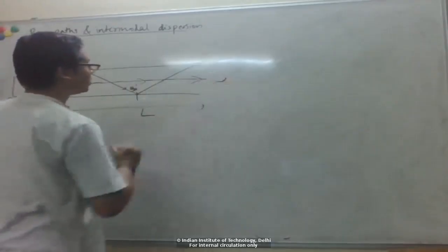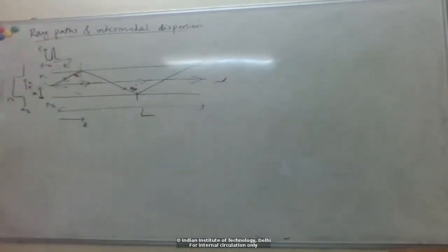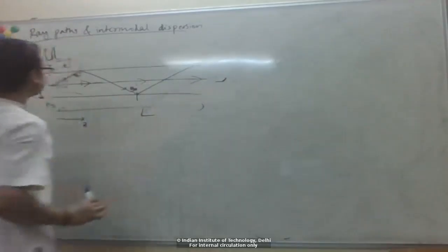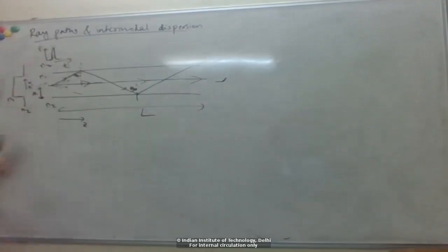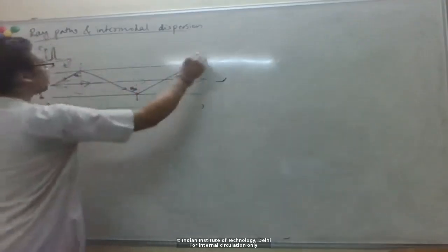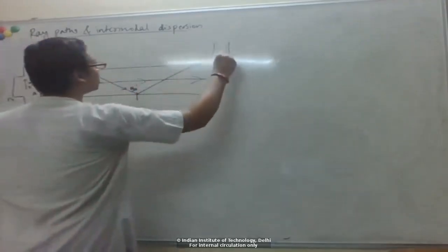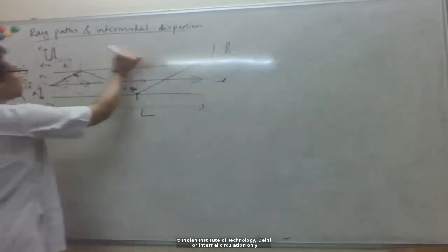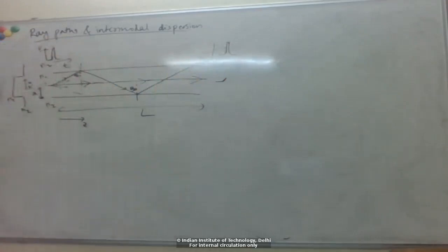So that fraction of optical power arrives first, but the other rays are lagging behind that, right? So if all of these traveled at the same speed, then at the output I'd just get this same pulse, because the whole optical energy travels together.